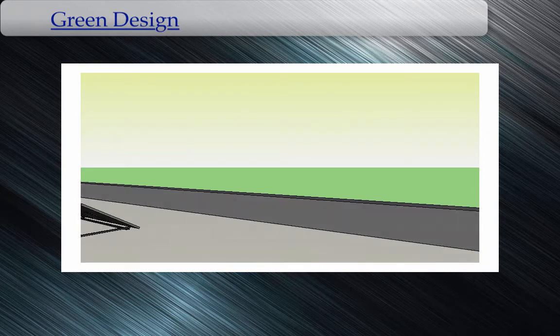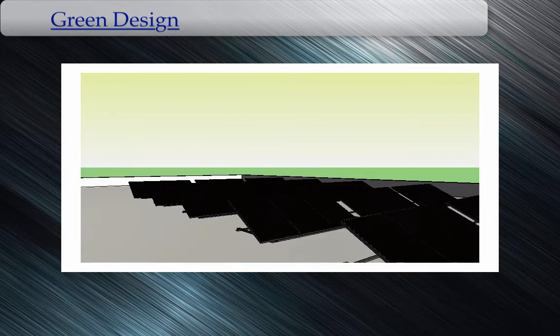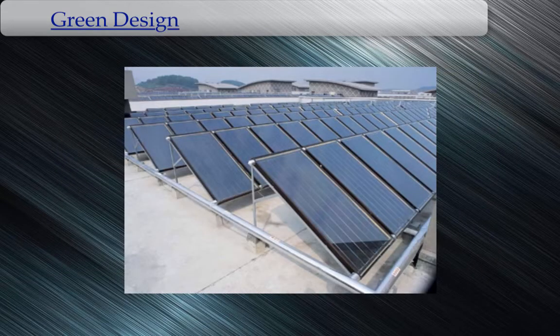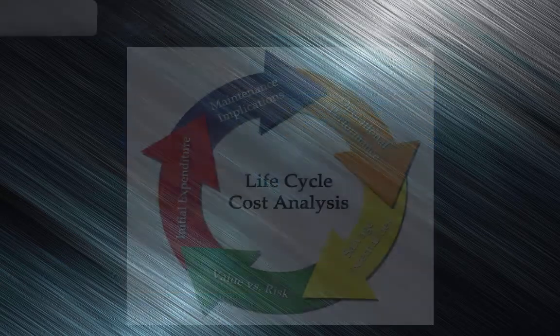The photovoltaic system will allow for an offset in energy consumption during peak hours and reduce costs spent on peak electricity rates. Both of these systems follow the guidelines listed under ASHRAE Standard 189.1, 2011, Section 7.4.1.1, and also award LEED certification points in the Energy and Atmosphere category for on-site renewable energy.